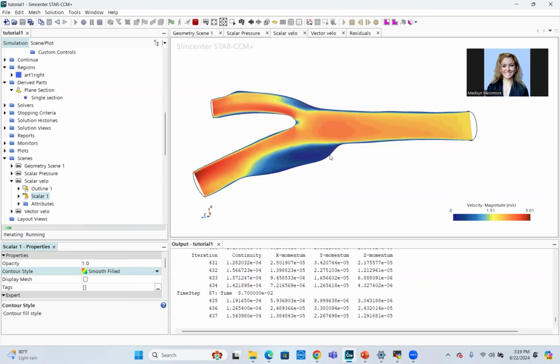And then it has to step forward in time, do another iteration on that outer loop, and then loop again at that same time step until it gets your level of accuracy. So there's a lot more computation that has to go on when you do unsteady because it has to solve it multiple times per time step that you give it, if that makes any sense.